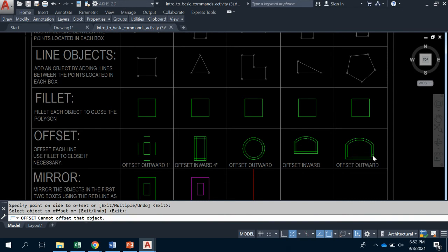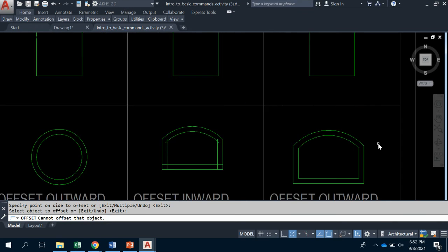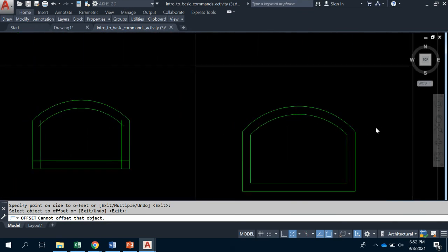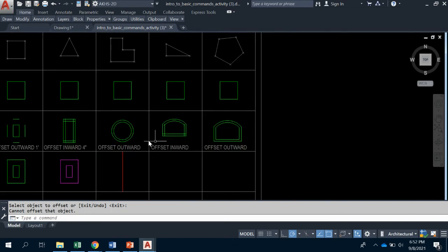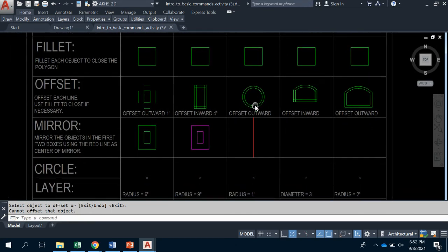And so you can see the difference here. This shape here was made with a polyline, whereas this one was made with individual lines. You can see it creates those gaps here automatically if you do it with a polyline, whereas over here with just your basic line, you have to do each individual line separately. So right clicking to escape or cancel that command and zooming out.